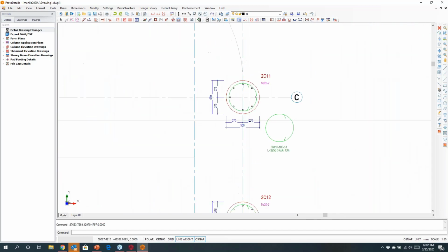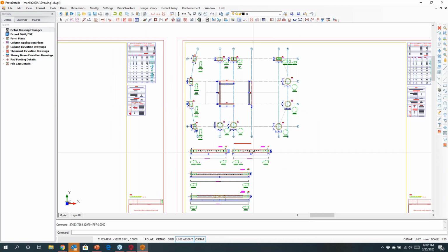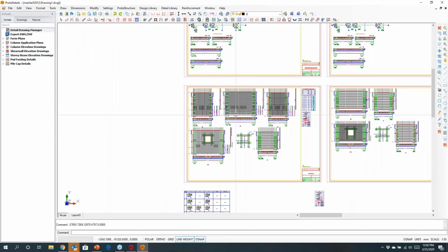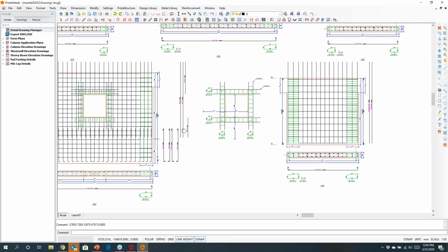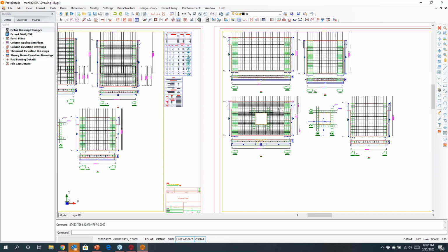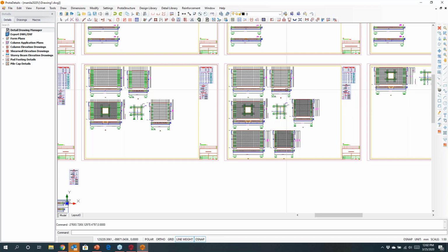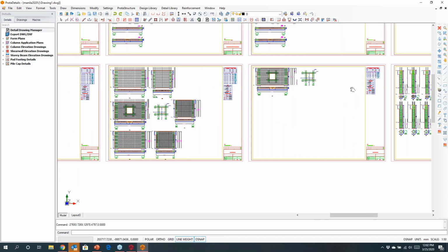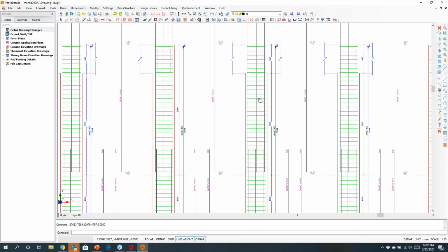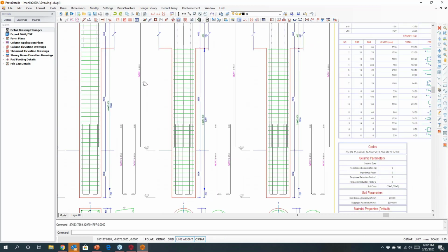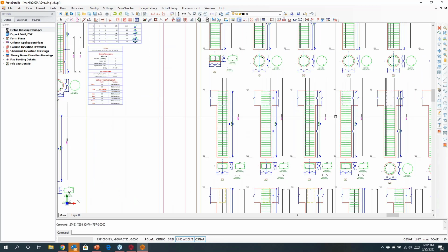You can produce different types of drawings. So if you want, say, set out drawings against grid, you can. But also here you can see other details like our elevations. All these are drawn up here, for the shear walls and so on. Where you've got critical height zones, these will be calculated and detailed accordingly, and you can see through here that I've created those. If you look at the columns there, again, you can see the detailing that's being performed for the columns. And we will look at containment detailing, and all of this will be included as part of this.